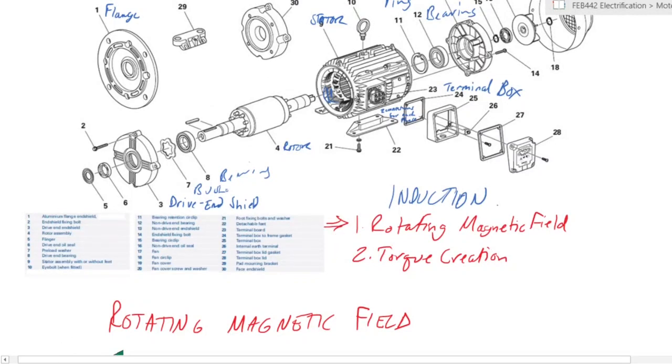Okay, well and good. You have a rotating magnetic field. How does that translate into mechanical energy? Why is it so important, right? Remember that this rotating magnetic field is an intrinsic property of your three-phase current, right? It does not require anything except for the mounting positions of the windings and a three-phase voltage or current applied.